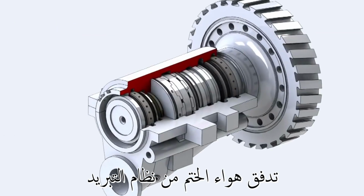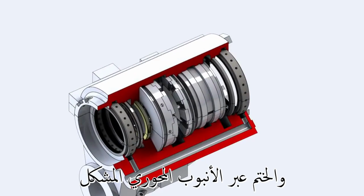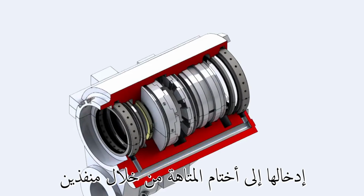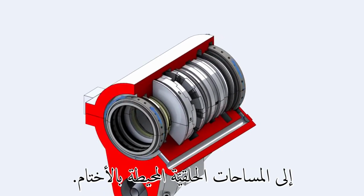The sealing airflow from the cooling and sealing system flows through the axial tube machined at the right side of the housing and is admitted to the labyrinth seals through 2 ports to annular spaces surrounding the seals.